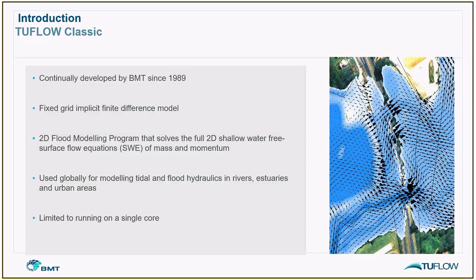It's been integrated with various 1D schemes, so schemes such as Flood Modeler and XP Swim, amongst others, and it's also been integrated with our own TUFLOW 1D scheme. It's extremely well benchmarked and well respected. One limitation is that the finite difference scheme is limited to running a simulation on a single core. The implicit nature of the matrices used to solve the 2D equations means that there are various interdependencies, which means that parts of the computation cannot be distributed across multiple cores or onto things such as GPU cards. And this limits the speed of the simulation and also makes very large model domains quite impractical.